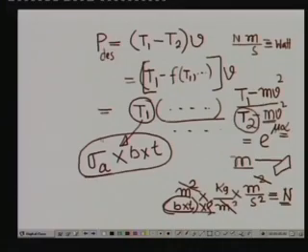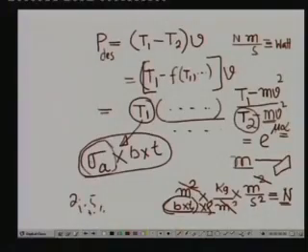How do you take the allowable stress? Either a simple way: you take something around 2 or 1.5 or 1.6, as I told you, or you can consider this particular sigma A from the design data book per unit length and unit cross section. These values will be given. Anyway, you are in a position to know this particular value.